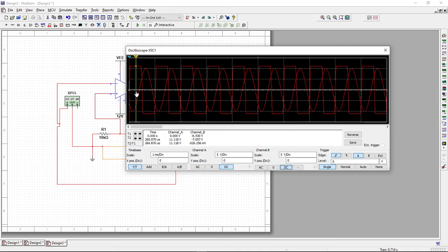That means I am choosing this second probe and keeping it at the intersection point of both. If I keep the probe T2 at the intersection point, it gives the output voltage as 6.528, that means nearly 6 volts. Okay, upper threshold point is observed as 6 volts.